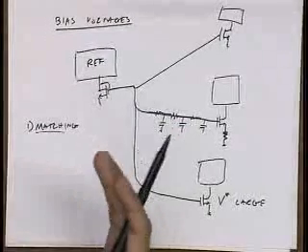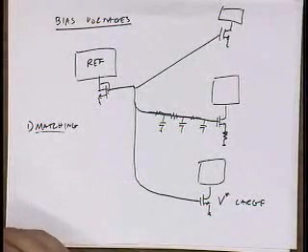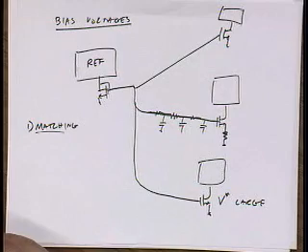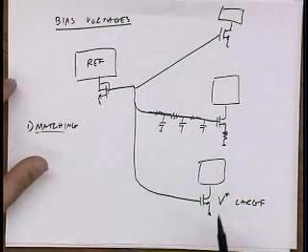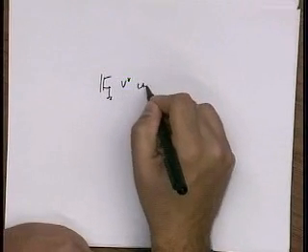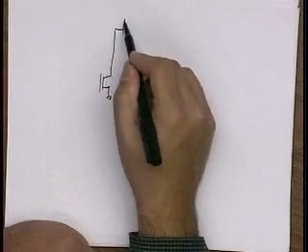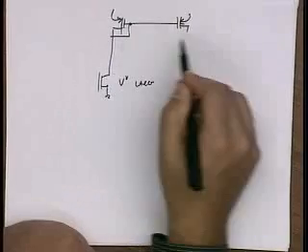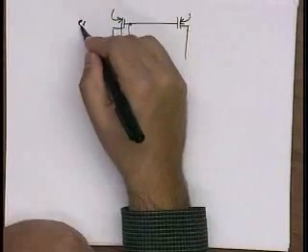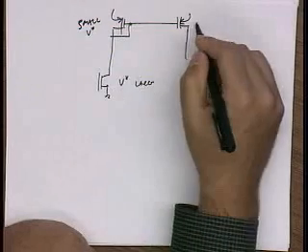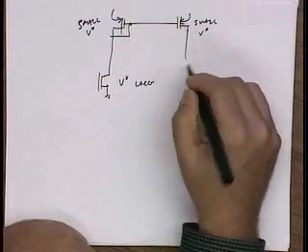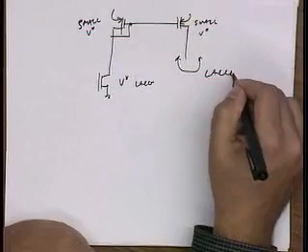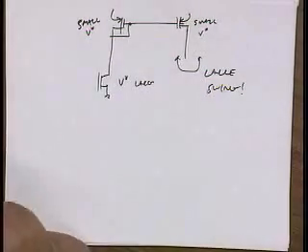Let's say you're willing to dissipate a little more power. I'll give you a hint. You can use the current and mirror it to another current source. Yeah, there's nothing sacred about this mirror. I can make another mirror, right? So I have my, let's say, my large V star device, and then I mirror it again. So this is a small V star device. And so here I have a large swing. Okay.